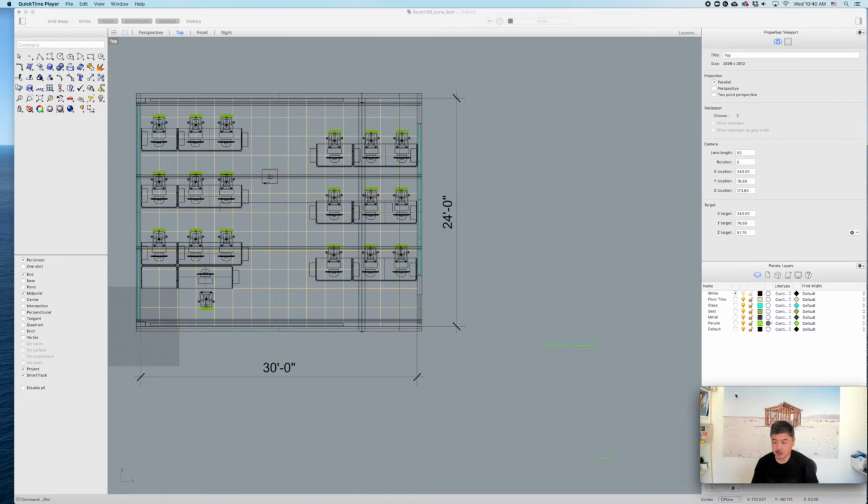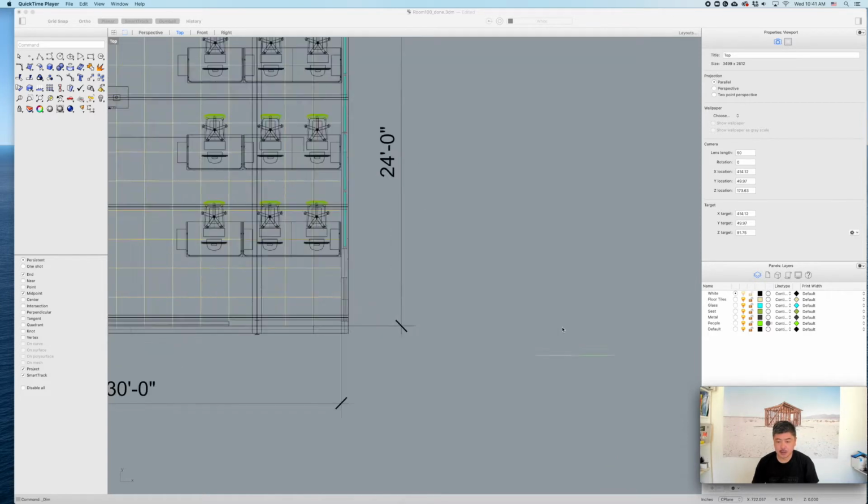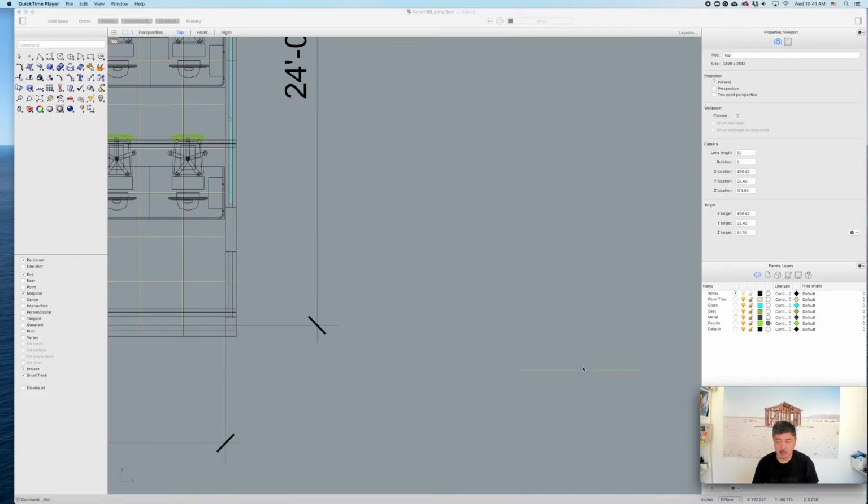Drawings will use specific layers depending on the line weights, and in Rhino the lines are represented as 1 pixel, which doesn't have any substance or thickness. So the line weights that you will see in the display window of Rhino are not going to have any thickness. So you have to identify each layer using the color that's assigned to the layer, and that's going to tell us how to differentiate the line weights. So you kind of have to do the translation inside of your head.